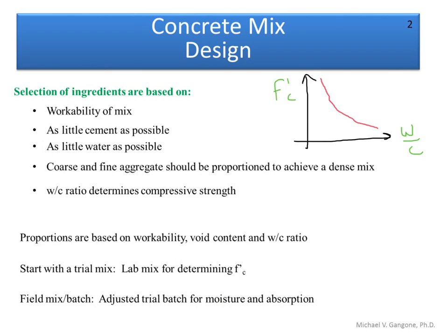Well, in that case, you have a certain water-cement ratio, and that water-cement ratio is going to give you an anticipated strength. Now, if I have some surface moisture in the aggregate, and I'm adding that aggregate into my mix, now I have all that surface moisture adding additional water into the mix. And what is that doing? That increases the water-cement ratio and decreases the strength.